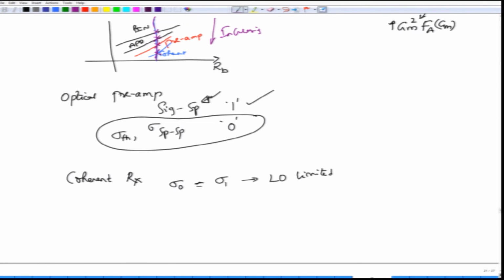The larger the resources you put in, the larger, in this particular case, would be the sensitivity of the receivers. So, this is what we wanted to talk about regarding on-off keying receivers, and we will end our module today with this one. We will later look at other modulation formats and some residual effects in the fiber that we have not considered, in the next modules. Thank you very much.